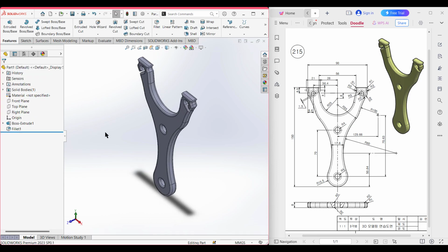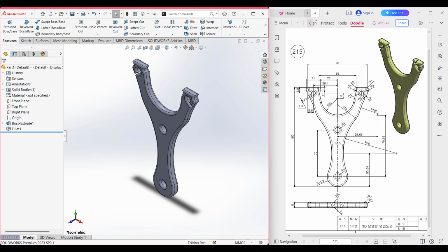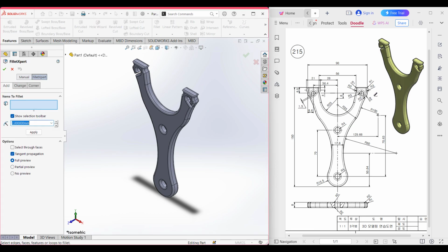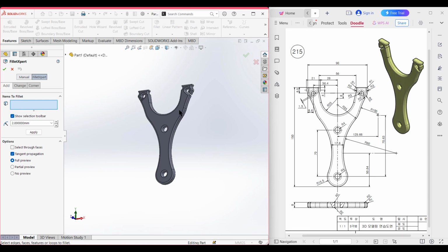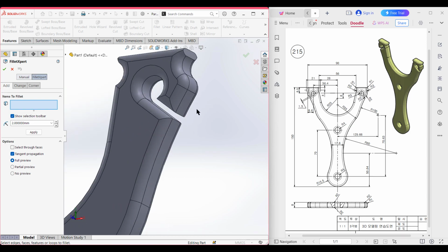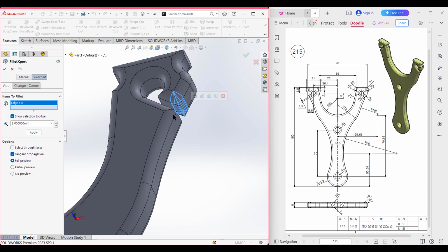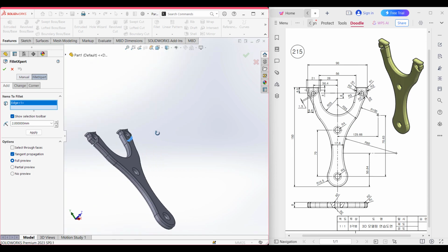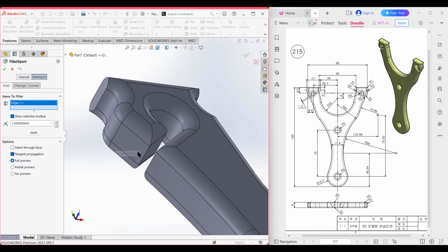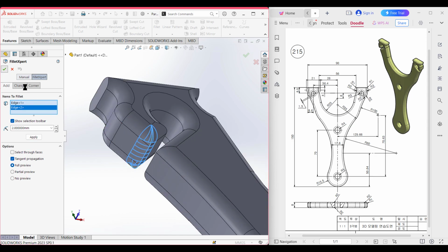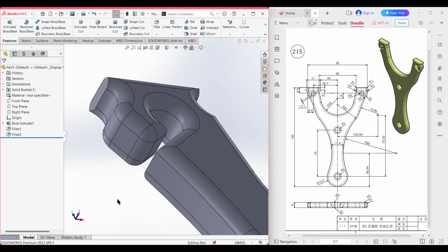Now isometric it. Now we can see it is quite looking like our sketch, this model. Okay, and you can smooth it by giving all other fillets. So I'm selecting the fillet tool. You can see it has a fillet of 2 radius here. You can also give that, so you can rotate it and zoom it, and you can give a radius of 2 unit here, and the same way on the other side also, zoom it here and give a radius of 2 unit here. Now press OK. Now isometric it for a better view.